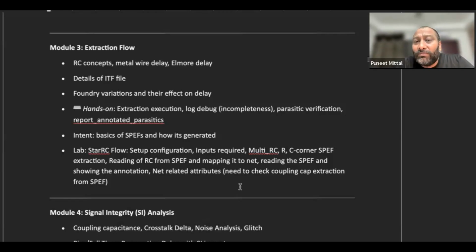We are also going to discuss the wire-related terminology, for example the width and thickness, and as a designer what you can change and what you cannot change. From the foundry point of view, how things happen, what the metal stack is, what the different types of capacitance are, the resistance, the modeling, all those things, and how they become part of the different modeling files. We'll even discuss the spec file, and how you are going to read it.